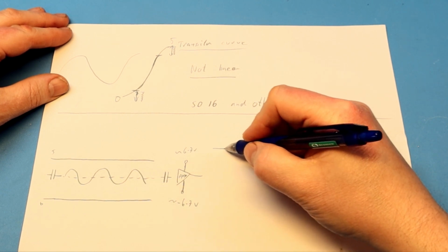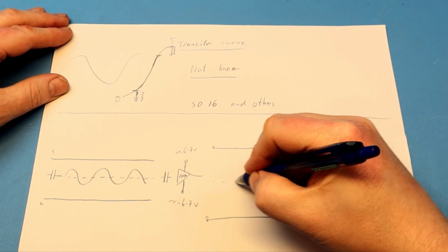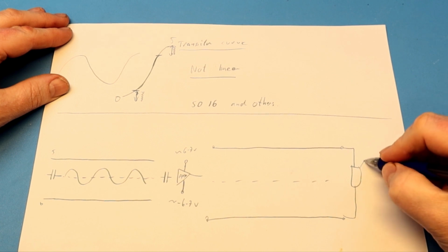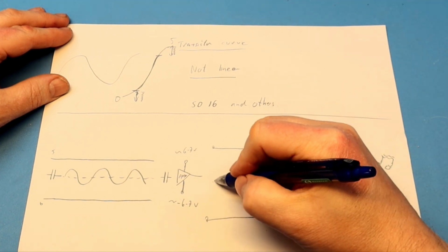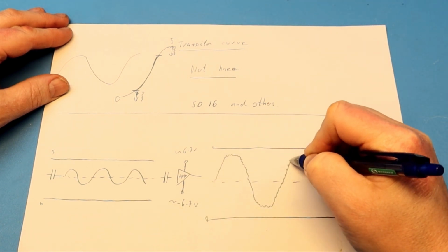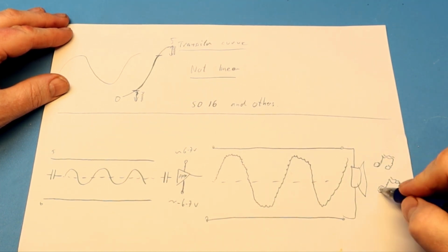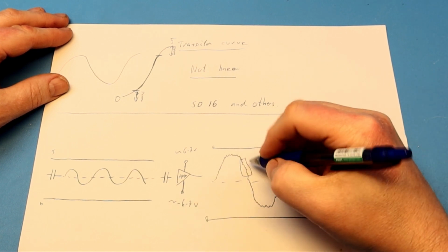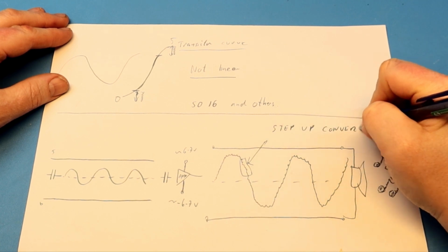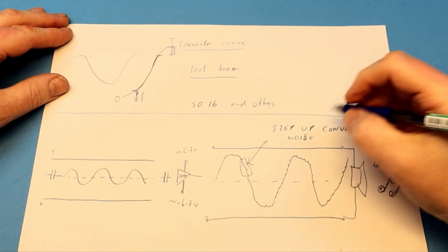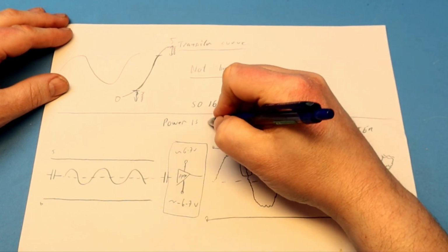But what they do is they use a step-up power supply and a symmetrical design amplifier via a switch mode supply or a charge pump to get a higher voltage on the output. And from chopping up the signal to make this, you will get some frequency disturbances in the signal. I try to illustrate that here by drawing these small inaccuracies in the sine wave. And this will be the noise level that the Sound Blaster 16 and some of the other clones and other Sound Blaster cards are riddled with.